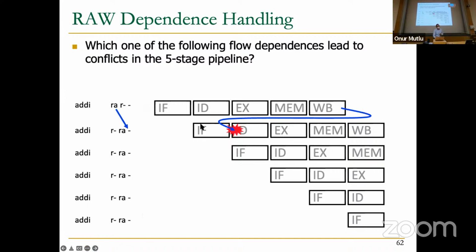So if this is the pipeline, you have a problem, right? These are cycles 1, 2, 3, 4, 5. You're decoding this instruction over here, and the first add has not produced register A. Write back happens over here. So you really need to delay the instruction. That's true also over here, right? Basically, these 3 instructions, if they proceeded in the pipeline, they would get the wrong values.